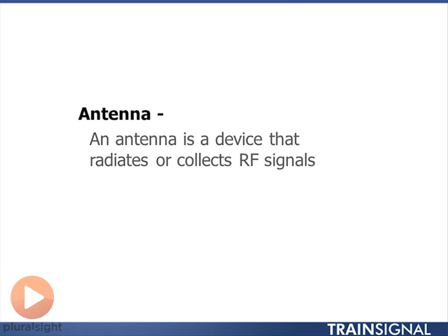So let's talk a little bit more about antennas. One of the most important things to realize about an antenna, which a lot of people get confused on, is that antennas are passive, i.e., they don't increase or boost the power in any way. What they're simply doing is taking the electrical energy and converting it to RF waves. However, the pattern that it forms when it propagates over the air is dependent on the antenna. And those different patterns are very important to understand in a wireless LAN.